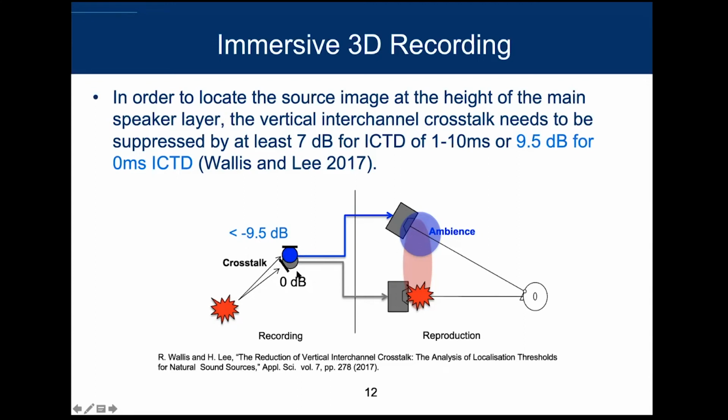And as I said again, spacing really doesn't matter. I'm not saying that you shouldn't use spacing at all. Sometimes you have to, but large spacing wouldn't matter. Maximum about 20 to 30 centimeters would be sufficient to create enough decorrelation, because decorrelation applied vertically is not effective below 500 hertz.